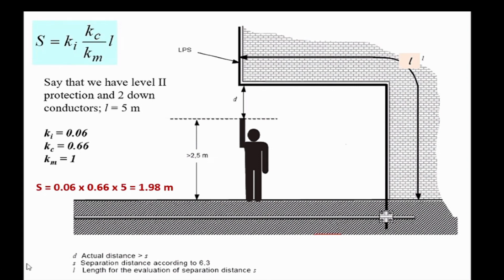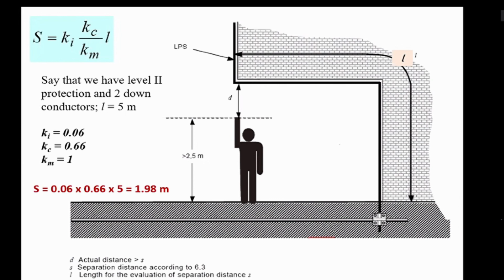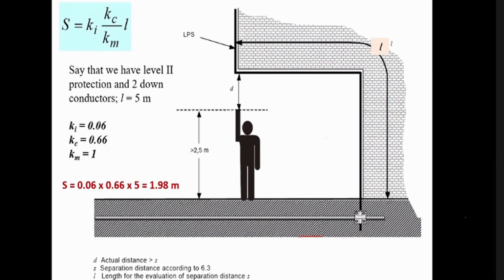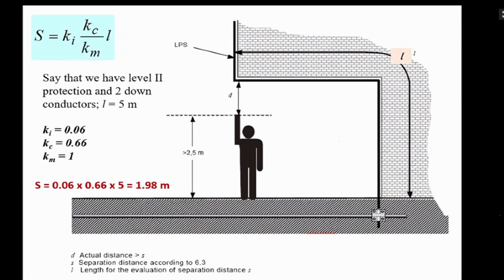I think it is not 2 meters. Sorry, I have to check my calculation. It can't be that much. Most probably it should be 19 centimeters. When I wrote it, I think I made a mistake. So there should be about 19 or 20 centimeters to avoid arcing.